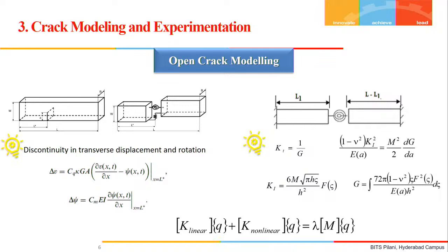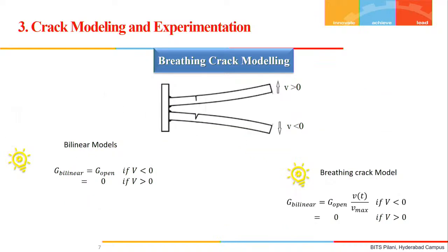This eigenvalue equation is nonlinear because the stiffness matrix here is nonlinear, and for the open crack, as we know, there is no time dependency of the stiffness, so it is quite easier to solve. Any general differential equation solver, Newton-Raphson or Runge-Kutta, will give the solution of this eigenvalue problem. This equation we have particularly solved by following an iterative technique, so we will get the final response, and we will see how this crack affects the responses.